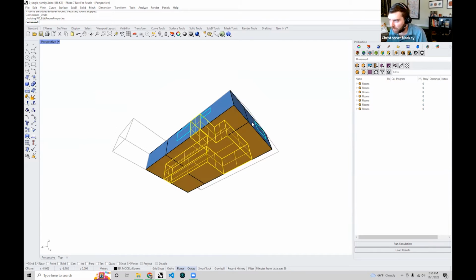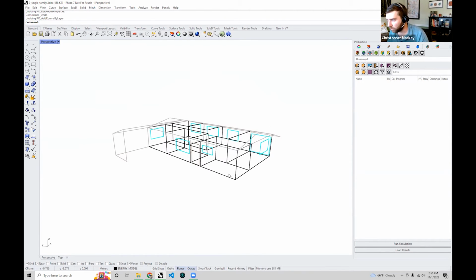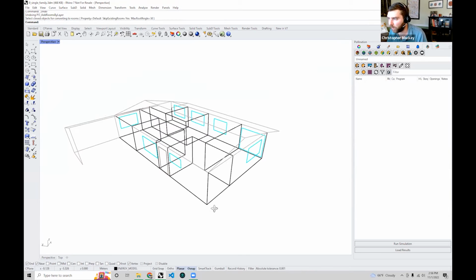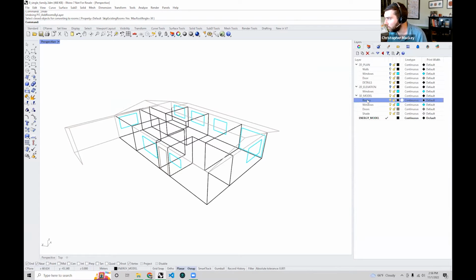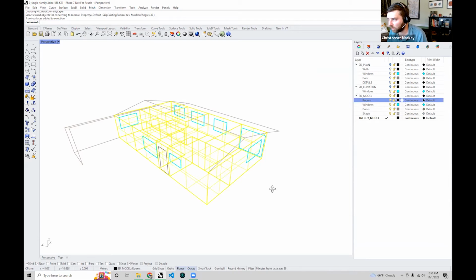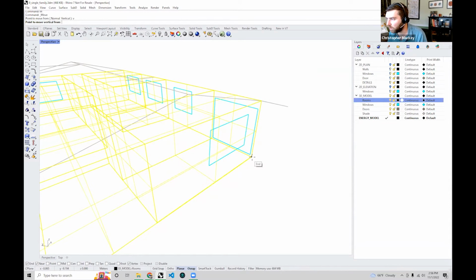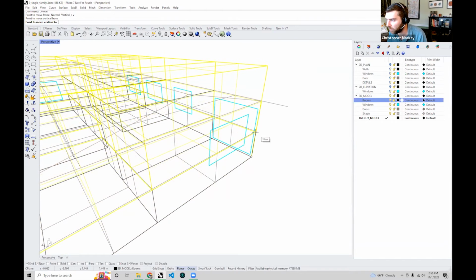All that you'd have to do in order to change that, I just hit Control-Z to make these no longer rooms. But what we can do is, if I go to add rooms and I say select geometry, or actually before I do that, let me just take all these rooms together here. I'm just going to click on the layer, select objects, and you don't need to worry about following along in this part. I'm just demonstrating how we come up with these defaults.